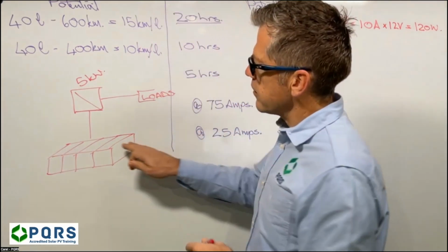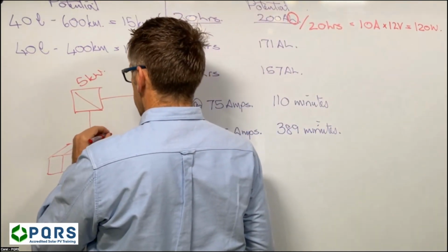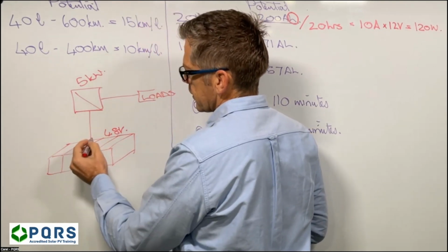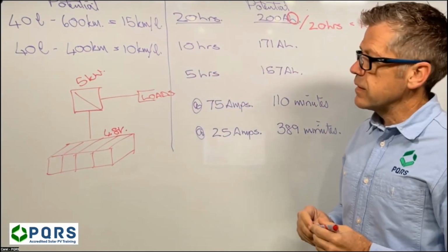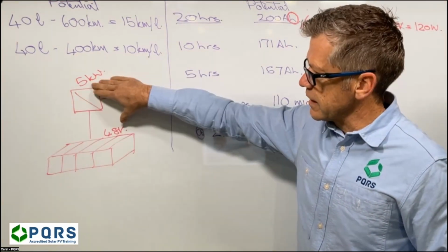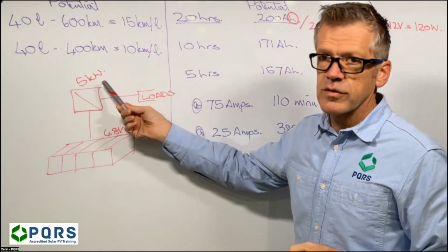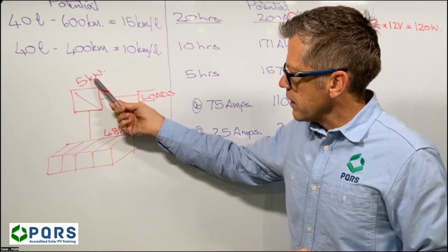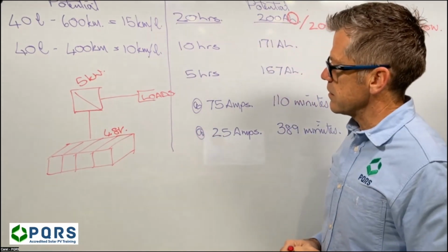You see them fitting 4 12-volt batteries, connecting them in series to generate 48 volts. And we see the 4 48-volt batteries connected in series to a 5 kilowatt inverter. This is what is typically happening in industry. We see guys typically using the Axpert range of inverters or the Voltronic inverters. A 5 kilowatt connected to 4 batteries connected in series.